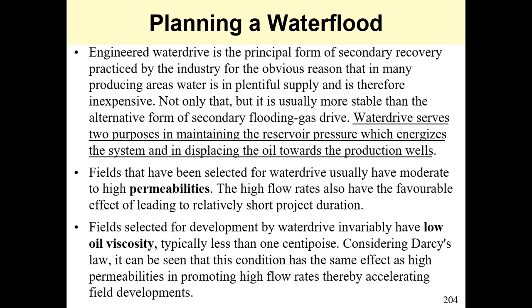The next thing is that fields with high to moderate permeabilities tend to be preferred for water flood projects. High flow rates have a favorable effect, leading to relatively short project duration.